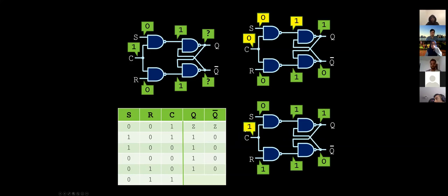And obviously, if I'm going to set C to 1, I'm going to get this 1, 0 here, and this is going to flip to 0, 1. So essentially, the high pulse here with the input 0, 1 is going to give us the output. Think about it: if I want to build a memory cell, if I set up the outputs the way I want, I just need to wait some time until C switches from 0 to 1, and then it would make sure that the output switches to 0, 1.